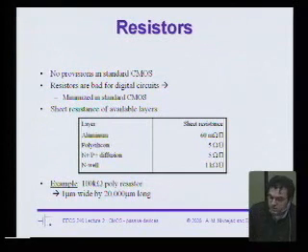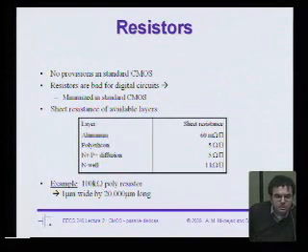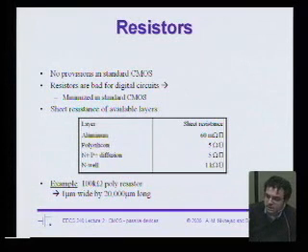Now, if you're using a non-CMOS process, there may be special thin film resistors available to you, which are basically materials that are not used in the standard CMOS process, but you can also always add them in post-processing. And if it's a really specialized process, you might even have provisions for trimming those resistors, like a laser trim, to get a very precision value. Okay, but that's rare. Most of the time, if you're working for the military, you're going to have to live with these different layers.